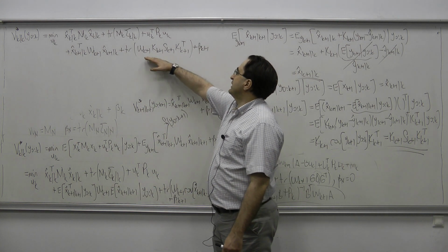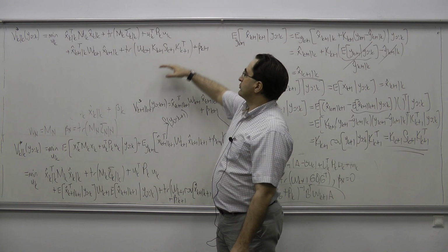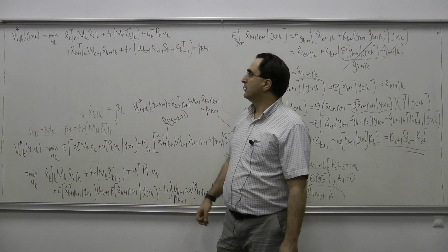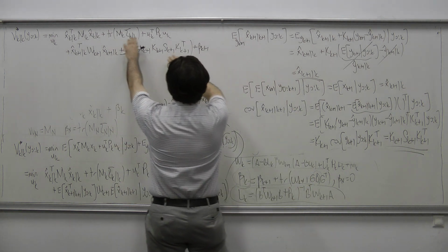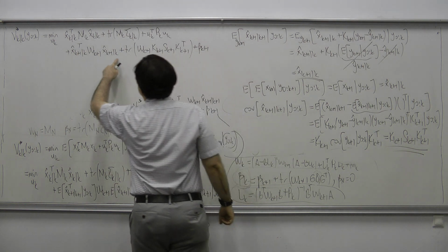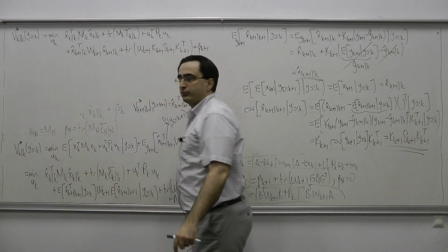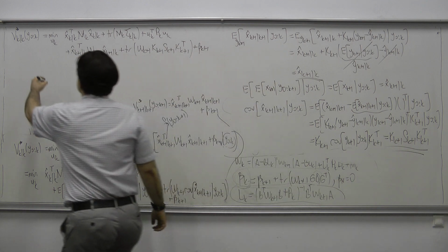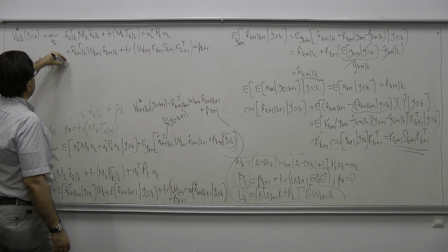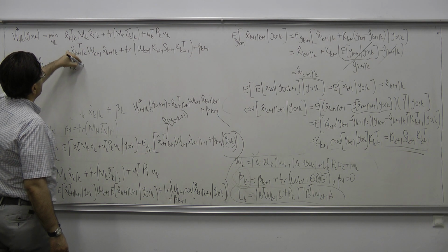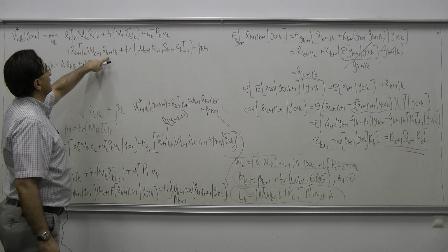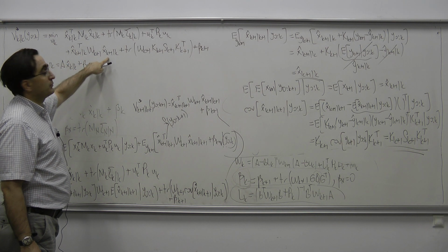So you see that these covariance terms are independent of input and the output. So these terms are going to go into the constant beta k. But in this predicted estimate, there is also the input term. We know that x at k plus 1 given k is nothing but A times x at k given k plus B times uk. So that is your uk here, hidden in this prediction.